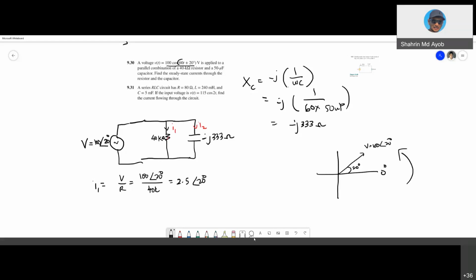Because as you can see, this is a resistor. So meaning that the voltage across the resistor is in phase with the current that flows inside the resistor. Please don't forget milliampere, because some of the previous students calculated it but missed putting milli here, so it will make your final answer incorrect.